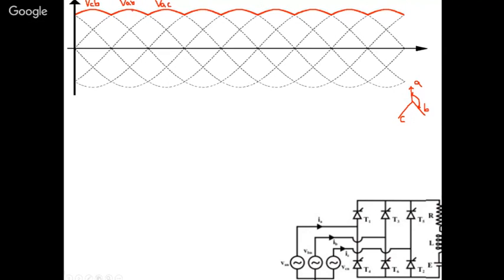So here A was positive for 60, again one more 60, it will be more positive, so VA. Okay, and here you see B was negative for 120 degrees, and here C became negative, so C will continue for again 120, is it? So this one will be VBC.